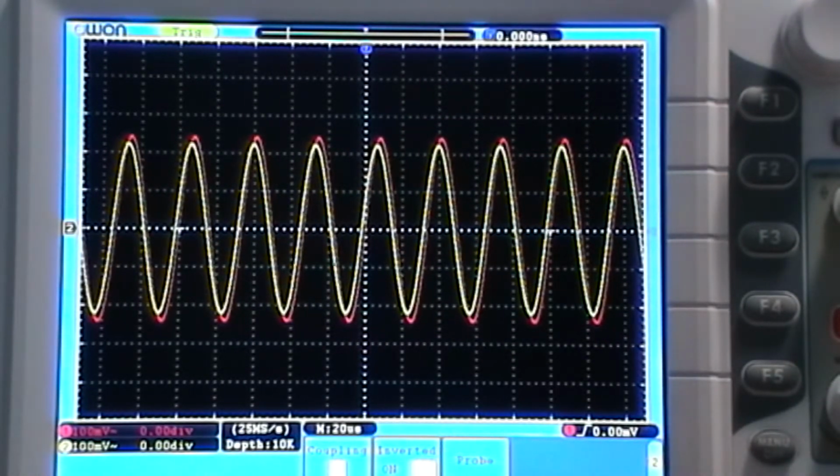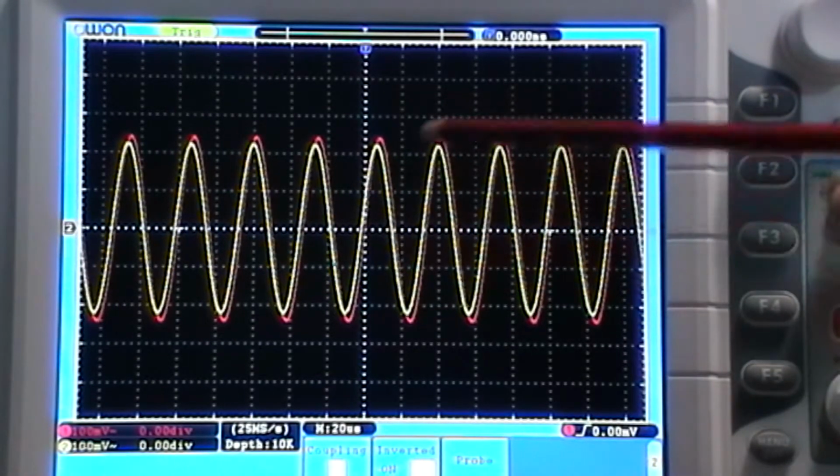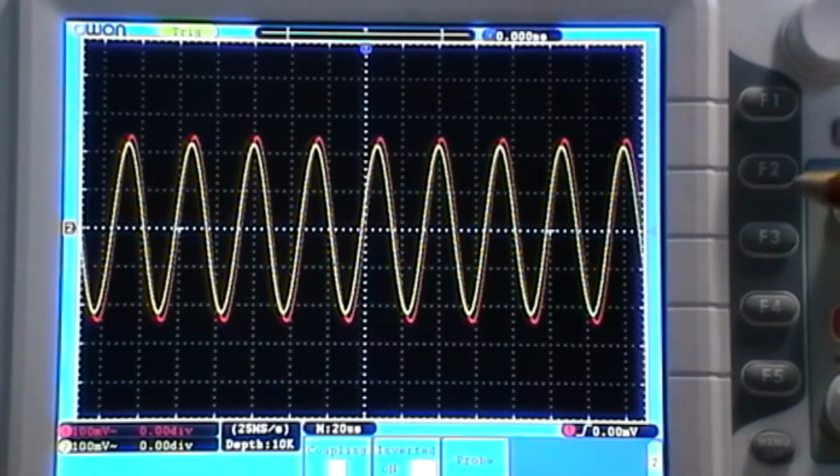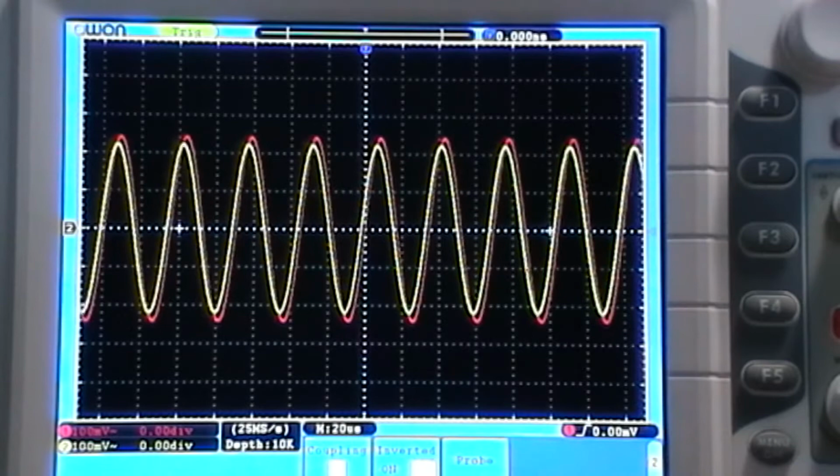So yeah, that's a good demonstration that the higher the capacitor, the more it allows the frequencies to come through, and the lower the capacitance, like this 15 nanofarad, it only allows the higher frequencies to come through. So we're only getting, like with this one, 10.6 kilohertz is its cutoff point. Below that, it just doesn't allow it to come through.